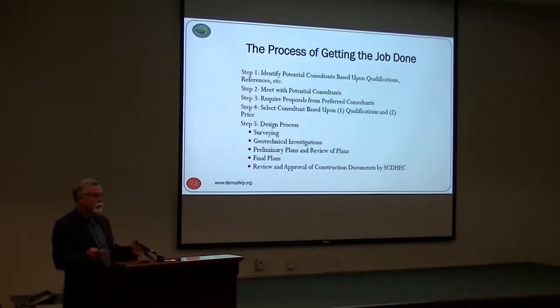And then after everybody agrees, they develop the final contract documents, which include the drawings and the specifications, something the contractor has to go by to remediate the dam. Before you can start the work, the DHEC dam safety office has to approve the construction documents. Then during construction, generally the same engineer has a resident inspector on site.